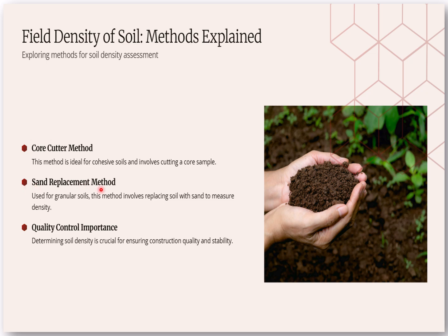The next method is the sand replacement method. This is used for granular soil, and this method involves replacing soil with sand to measure the density. It is also known as the field method. Next, quality control importance. Determining soil density is crucial for ensuring construction quality and stability.